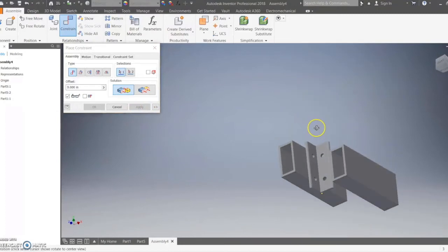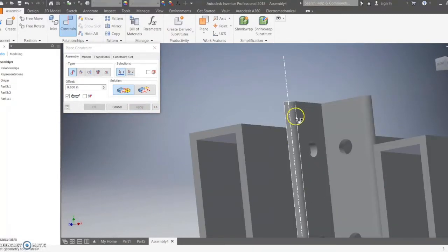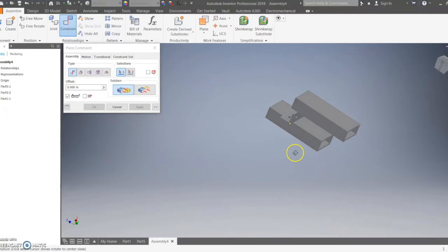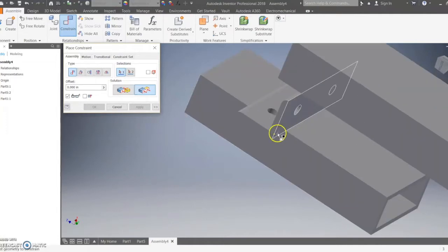If you look here, this doesn't look right. You have the part on the other part, but you can see that this is going off the edge, which makes it look a little awkward. So the best way to deal with this is to flip this 90 degrees so that this is flush with this. Which brings us to the next type of constraint, a flush constraint, which basically makes sure that the 2 objects you select are flush. This requires you to select 2 faces because you can't really flush an edge. An edge can be flush into another face in many different ways.